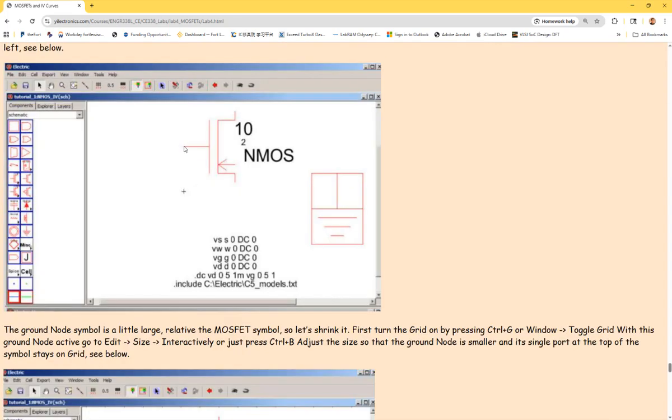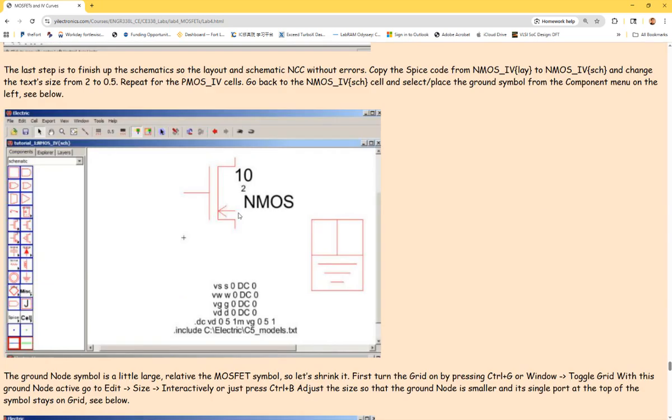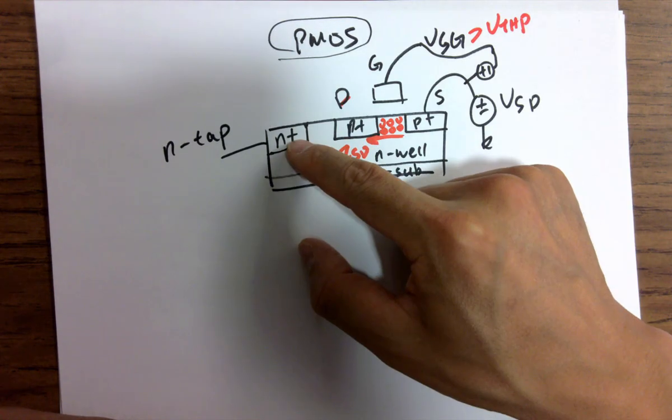And sometimes if you don't specify the well connection or the body connection, you can have a force terminal on the device. You can see you right click and there's the option, I think. It shows you how to do it, but we didn't have any problem in the past. So it just follows instructions and you can introduce the force terminal over here. And what is that force terminal? It's a body connection. It's actually the well tap. It's a well tap, okay?